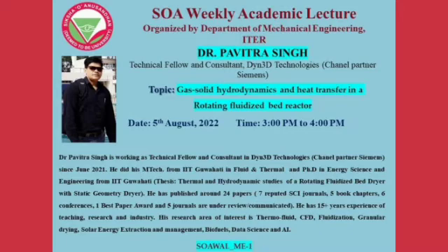So at various points I have selected P1 to P16: right to chimney outlet direction, top to chimney outlet direction, left to chimney outlet direction, and bottom to chimney outlet direction. In all these four directions I have selected these 16 points to measure the pressure, temperature, velocity variation, volume fraction, suspension density, etc. Also I selected 8 points in the radial direction to measure the variation in the radial direction.